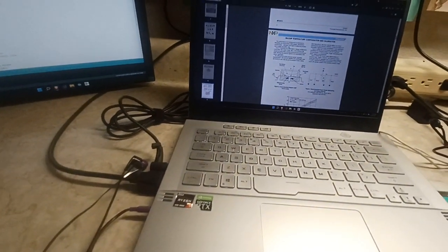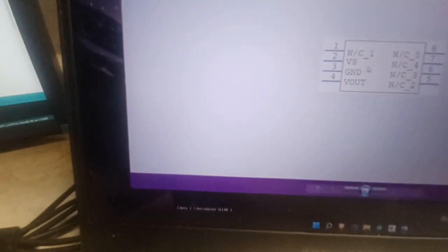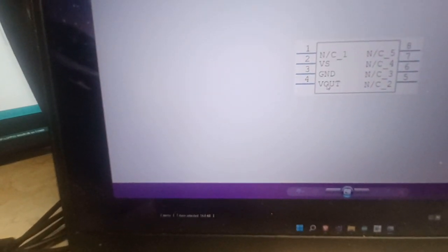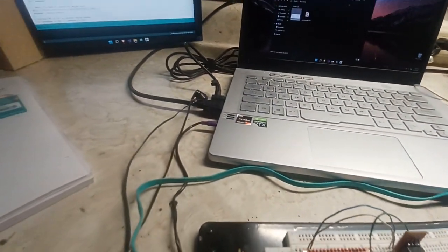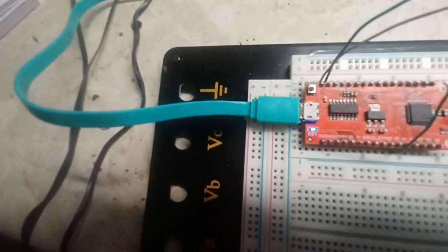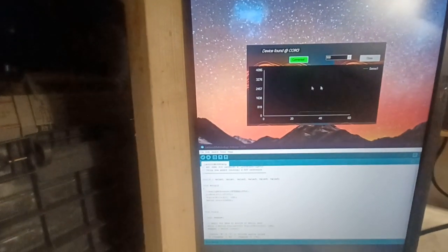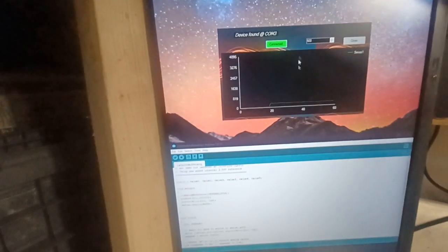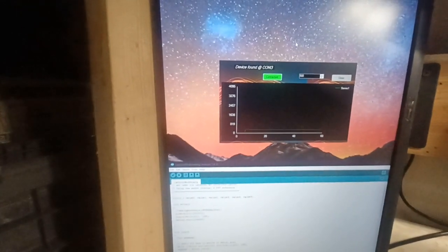And the pinout is just this, right? It's got 5 volts, ground, voltage out. Very simple, straightforward connection. So if I were to connect to it, that is the current pressure at the port. And you can see the LED on the Arduino is blinking. That's because I am requesting the values every 500 milliseconds. So this is the Visual C# form, and I got a background image on it. It kind of looks like I wanted to make it look modern, sort of.